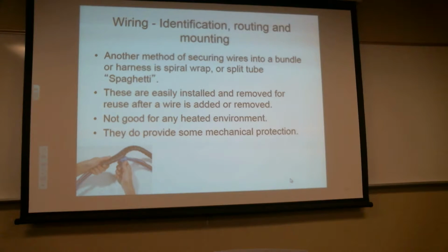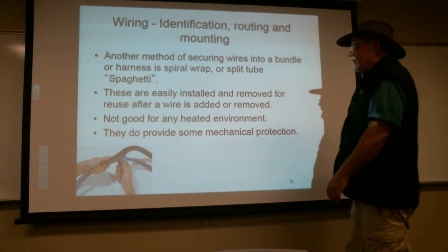Not many, until they're on fire. Once the thing catches on fire, substances like polyvinyl chloride not only readily burn, but they release all kinds of nasty toxic substances. So if that's going to be in an area that doesn't normally get very hot, it's probably an occupied area. So now all the rules around fire protection come into play. These are things you all kind of got to consider, however it may have been done.